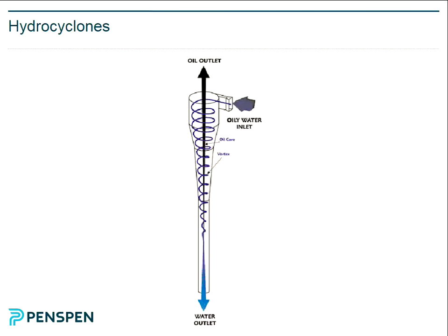So that's oil treatment; now gas treatment. Why do we need gas treatment? We need it to reduce water content, to prevent water condensate and hydrate formation, to lower the hydrocarbon dew points, and to prevent condensate of heavy hydrocarbons. So we're taking out oil, we're taking out water, and preventing hydrate formation, potentially by the injection of hydrate temperature depressants such as glycols and methanols.